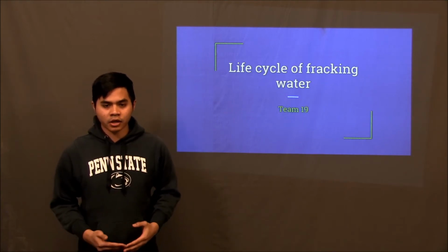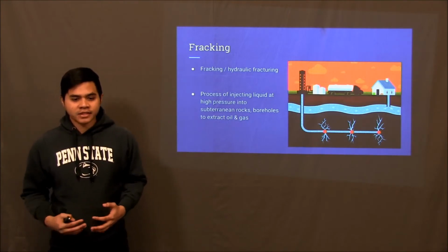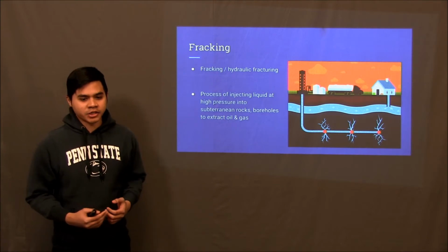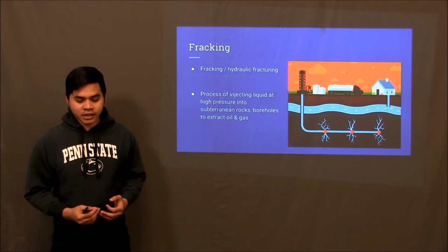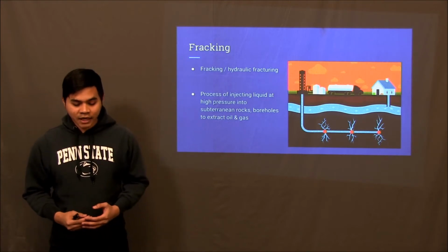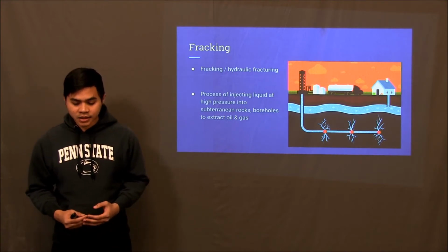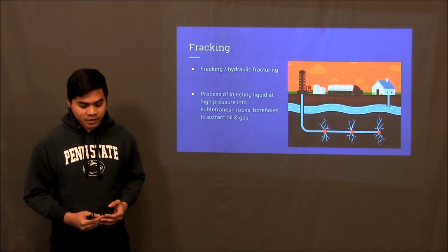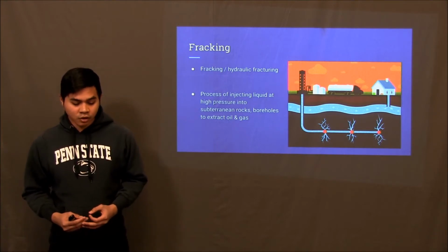in our own backyard. So fracking, or hydraulic fracturing, is a process of injecting liquid at high pressure into subterranean rocks and boreholes to extract oil and gas. Specifically, it is a well stimulation technique in which rock is fractured by a pressurized liquid. The process involves the high pressure injection of fracking liquid, primarily water containing sand or other proppants suspended with the aid of thickening agents, into a well bore to create cracks in the deep rock formation through which natural gas, petroleum, and brine will flow more freely.